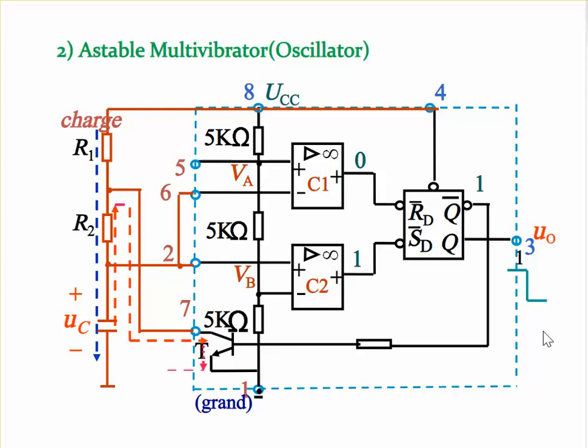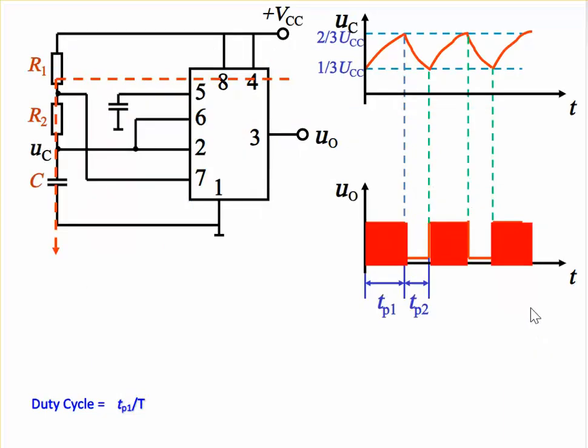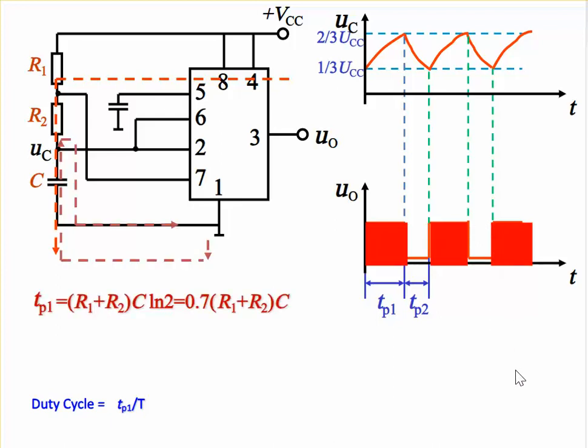Similarly, this is going to take place again and again, and you will have the astable multivibrator developing ones and zeros correspondingly. Charging and discharging will develop 0 level, 1 level, 0 level, 1 level. This is going to get repeated, and these ones and zeros will make the waveform go from high to low, low to high, high to low, low to high. So it will develop a square waveform. This is what is happening: the charging and discharging of the capacitor between the levels of 2 by 3 VCC and 1 by 3 VCC will go for 1 and 0, 1 and 0, and that develops a square waveform. That is why we call the astable multivibrator a square wave generator.